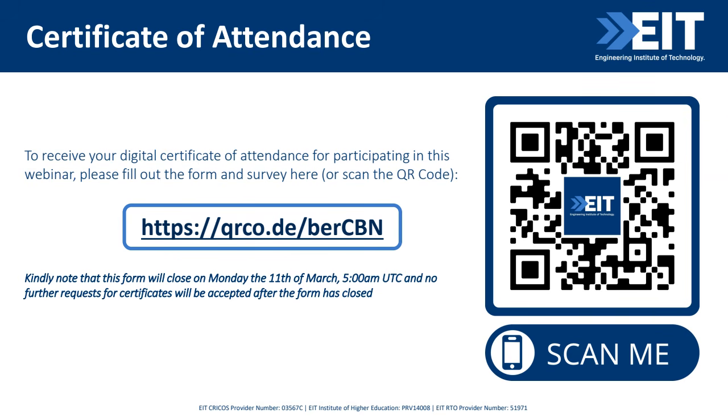One of the problems when we do control is that we take the action and it's already late, so we spend more energy. It's a problem on its own, and you have different options in it. If it's in a heating application, I would say rely heavily on predictions: predicting the target temperature, predicting the temperature outside over the next few hours, and then designing a controller that is smart enough to take these into account.